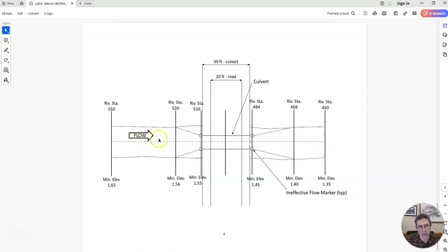As the flow comes down here, it's filling the width of the river, but it's got to narrow down into this culvert. And so HEC-RAS has to have sort of this triangular or angled line that's narrowing the flow into the culvert, where in this triangle and this triangle there's not really flow occurring. Okay, so we're saying on the outsides of these 2 markers there's no flow occurring in this space. Okay, same here and same here. And you can see this in reality by these little eddies that show up in the river.